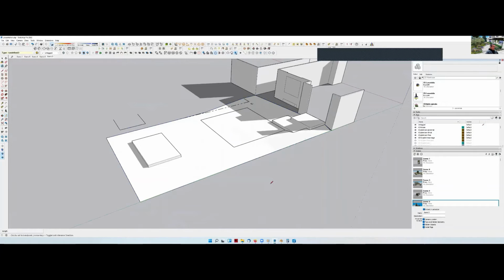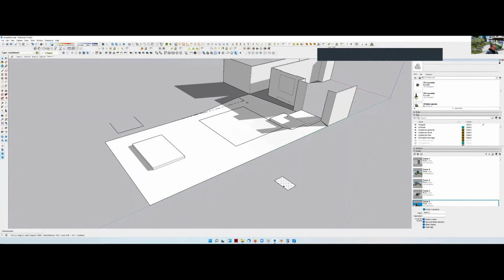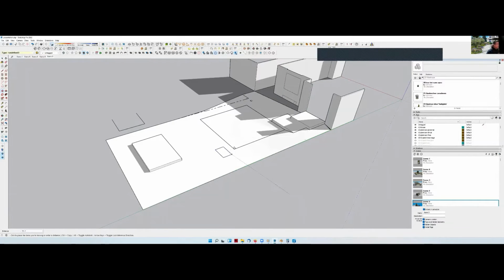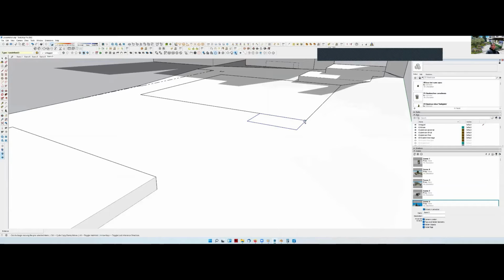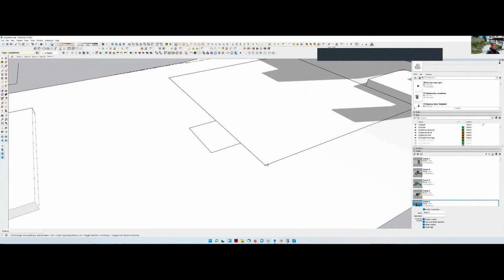Then I'm going to create a 3 foot long by 2 foot stepping stone, and we're going to make that 2 inches tall. I'm going to triple click it to select all the faces. Then I am going to make this a component. Due to the fact that I'm repeating this object a few times over in my model, components actually work a little bit better for that. So then let's move this, and we'll line that up actually with this over here. And then I'm going to move this off 4 inches.